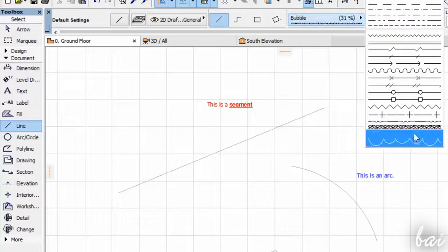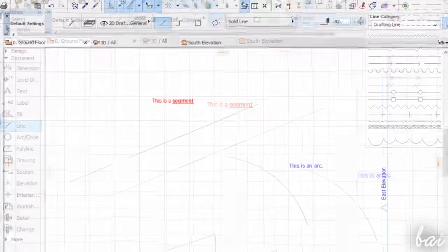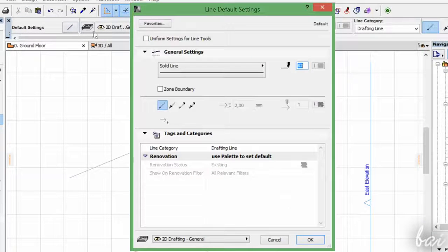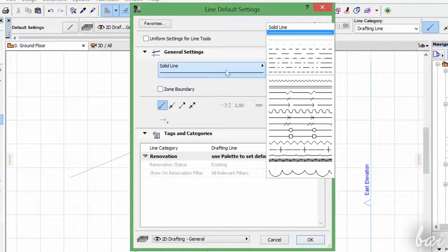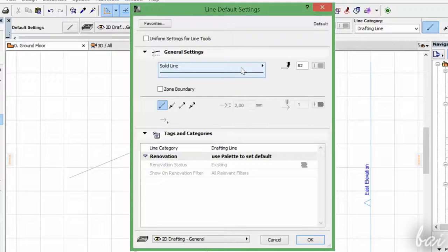For all the list of properties, simply click on the button inside Default Settings. ArchiCAD does help you while you draw. For example, nodes and vertices are represented through check marks, points on paths through a star, and segment medians through an horizontal mark.